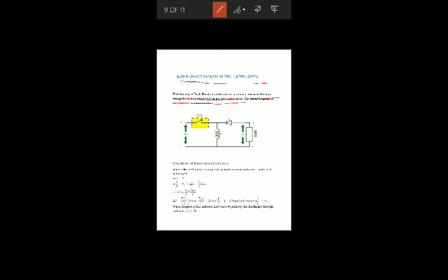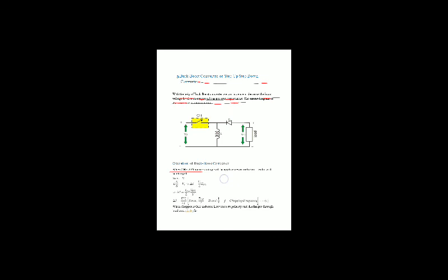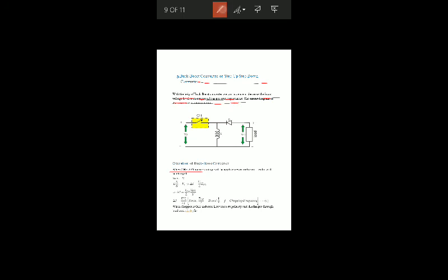First condition, when the switch is on, voltage is applied across the inductor. Because the diode is reverse biased, it acts as an open circuit, and the inductor will charge.